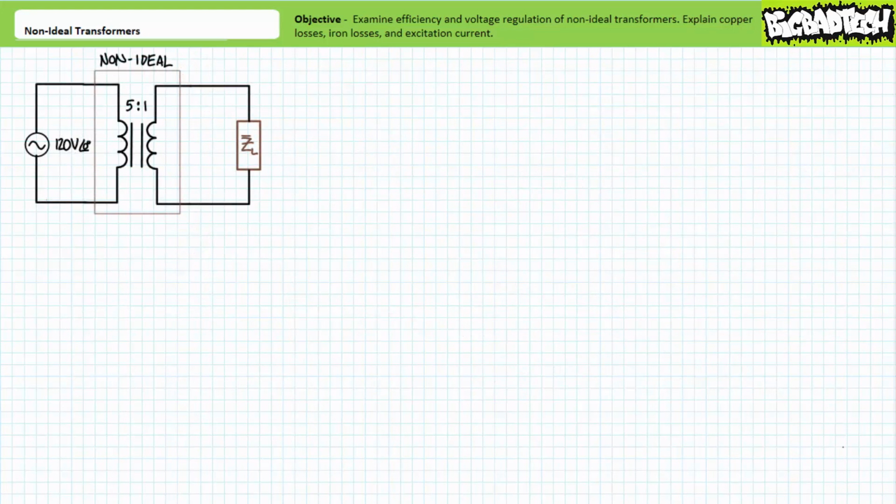Moving on. As you're no doubt aware, any reduction in voltage reduces current, and power, being the product of voltage and current, will take a double hit. This is perhaps the larger point of the preceding section. Yes, efficiency, even for crappy transformers, is respectably high. However, output voltage isn't constant for a non-ideal transformer, accounting for imperfections.